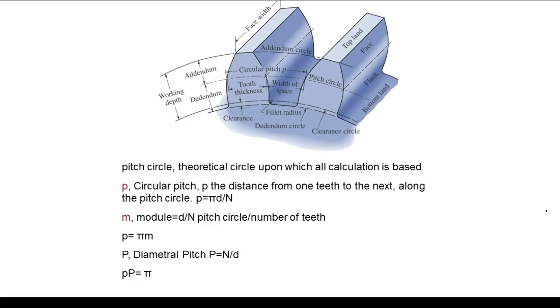This is what you have to understand when you get gears. These two gears are going to have to mesh together. So what that means is the spacing between the gears and the width of the gap, and of course the pitch of the face of the two gears have to match. That makes sense? Yes or no? Because if the spacing in the gear teeth, the pitch and everything don't match, that means the gears are not going to mesh together very well.